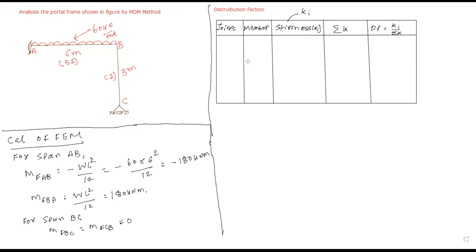Fine. We have only one junction where a minimum of 2 members are there. Which junction is that? Write down in chat box the name of the junction where a minimum of 2 members are there. Fast. Okay, so we have only one joint, B. At that point, a minimum of 2 members are there. So I need to divide this table into 2 parts: for junction B, left support AB, and down support or right support, that's CB. Yes or no? Let me start the calculations.